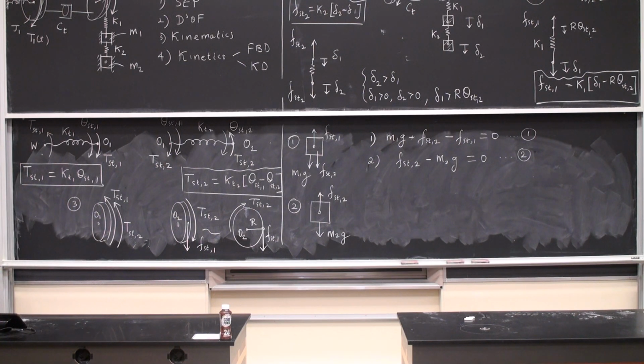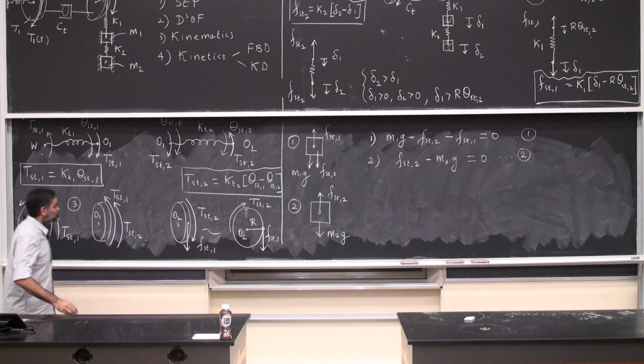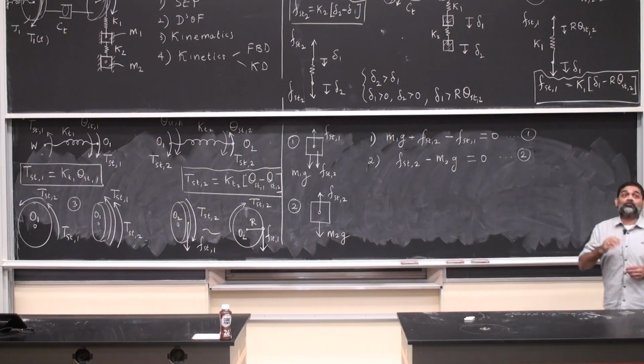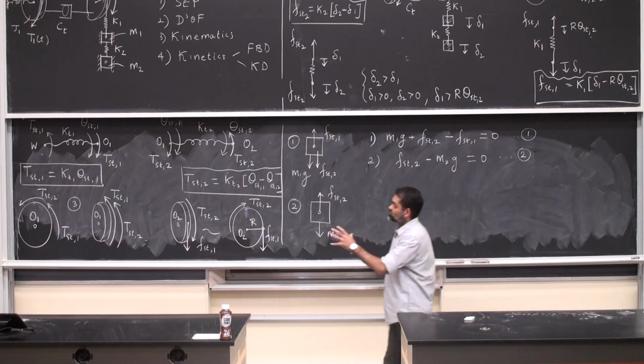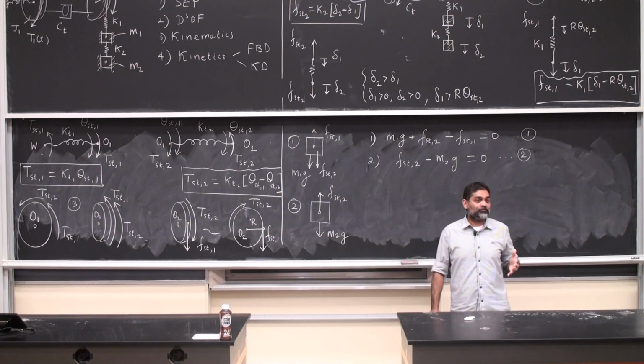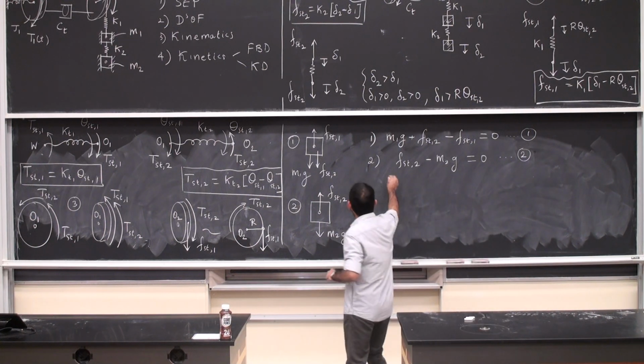From here, if you want, you can draw the circle view. This is the torque, T static 1, T static 2, that's O1. If I sum the torques about the point O1, basic statics, both the torques are acting in the same sense, so I'm just adding both of them up and setting them equal to 0. Okay? Hang on.